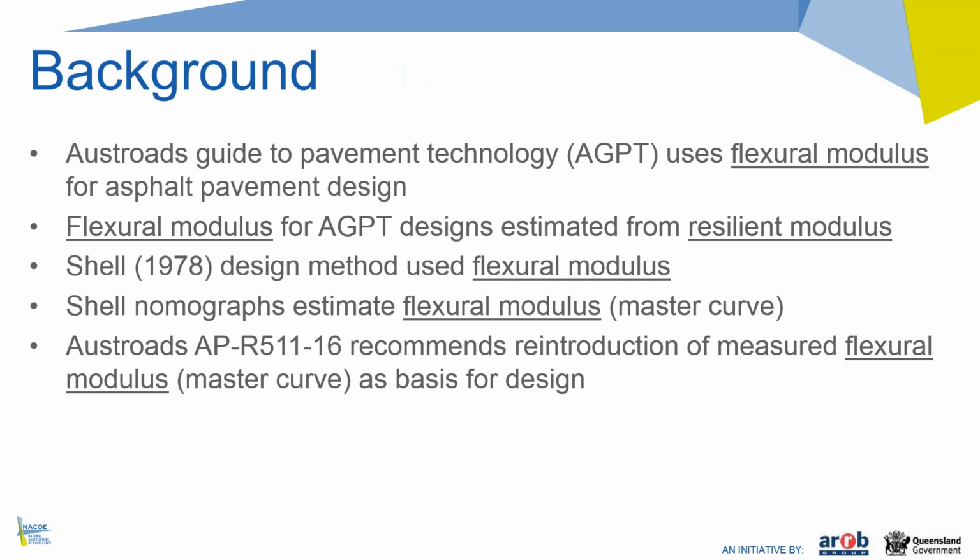So if we take a step back and look at why we can do this, the current Austroads Guide to Pavement Technology actually already uses the flexural modulus. It's always been the basis of the design method. It's just that we estimate the flexural modulus from resilient modulus values because in the past we haven't actually measured flexural modulus.